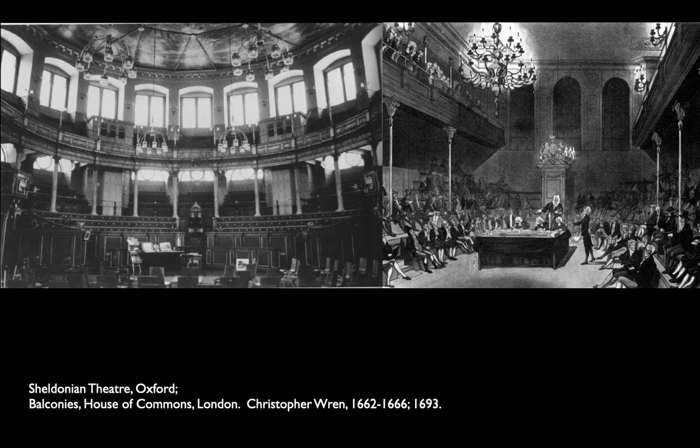Now he also uses it in the Sheldonian Theatre, this theatre that he designs at Oxford, for the columns. Those are cast iron columns that are holding up the balcony. And a little bit later, the now demolished House of Commons in London. And in both cases, just like the churches that he and Hooke designed throughout the City of London, the important thing is to get the columns as small as possible so that they restrict views as little as possible. And cast iron is perfect for this because it's so much stronger than brick, so much stronger than stone. You can support the same load with a much, much smaller cross section.